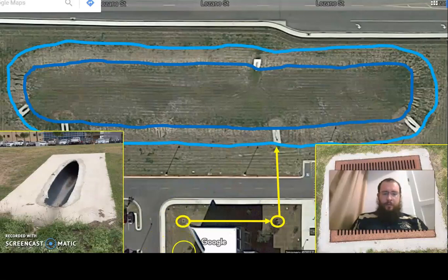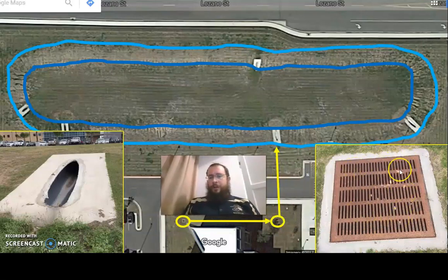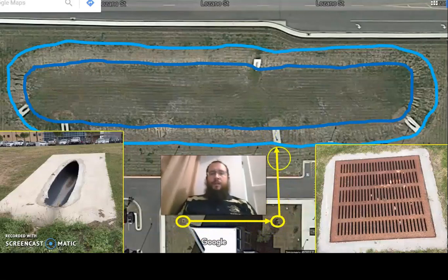And then there's a pipe that goes under the ground here and connects back to all these other little drainage pipes that are there. Underground, it connects by pipes. The closer it gets to the ditch, the deeper it goes underground before it comes to this exit point.